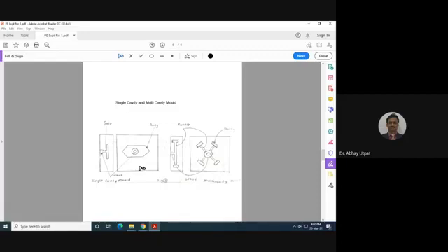This is a schematic diagram. These two views are shown, side view and front view. If you see from the front, or you can say top, whatever it may be, from the front side you are observing this is your cavity, and as your screw is perpendicular to the paper, it is shown. But if you see from the side, this is the cavity, this is the gate, and this is the screw. I hope you are getting my point. Single cavity mold. This is the cavity, the screw and runner are perpendicular to the plane of paper, which is observed here in the left hand side.